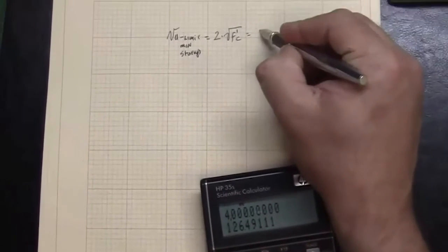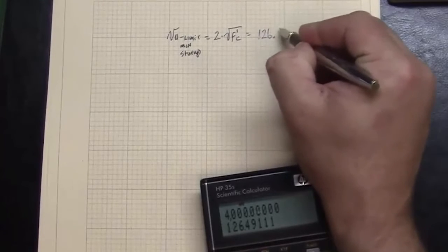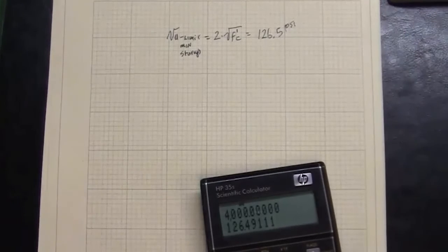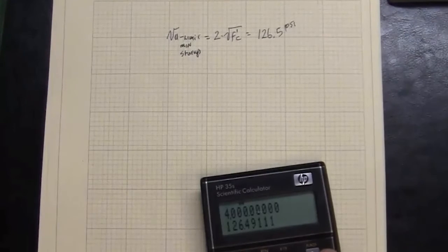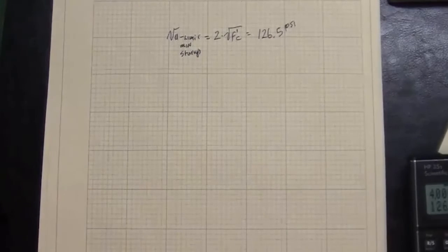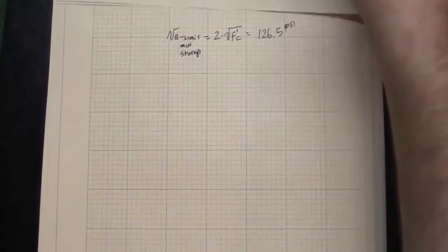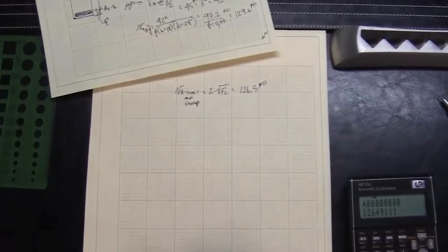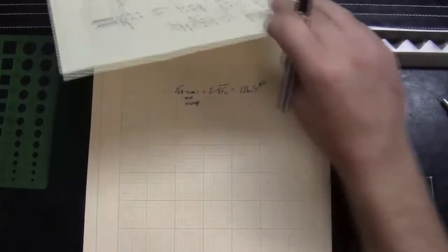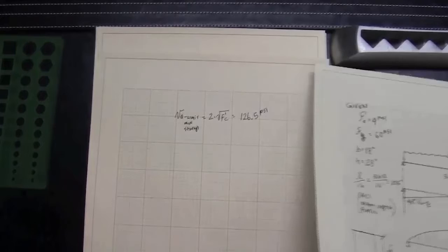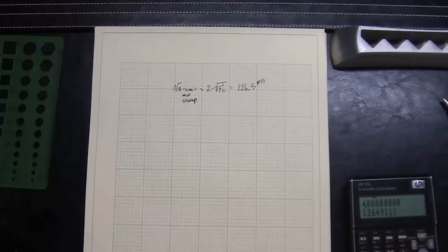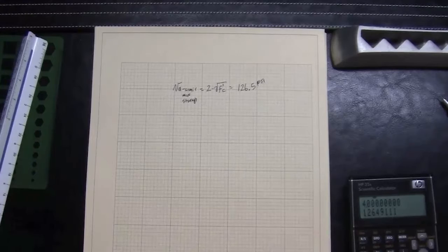My threshold for minimum stirrups will be 126 psi, so I'm at 129 in my example. So it's really just going to be minimum stirrups required. So this will just be a preliminary pass. I'm trying to find out if our solution is workable geometry-wise as we begin to validate the design.